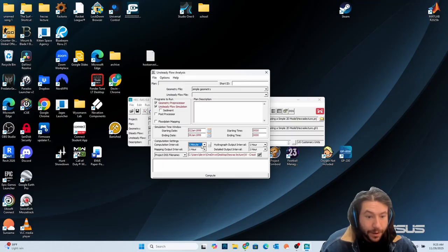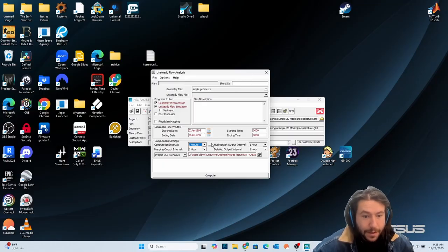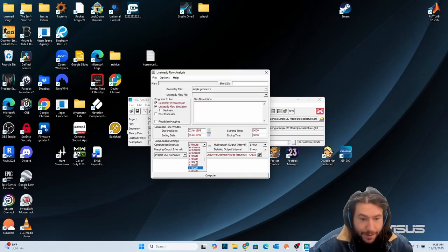So this is a super important parameter for the equations. So if you're having issues, you're having errors pop up, it's normally going to be this. If you aren't able to find the error in another thing that I've shown you, like the red dots and other things, this number is usually the problem. You can usually decrease this, and it will fix your errors that you're getting in your computation.